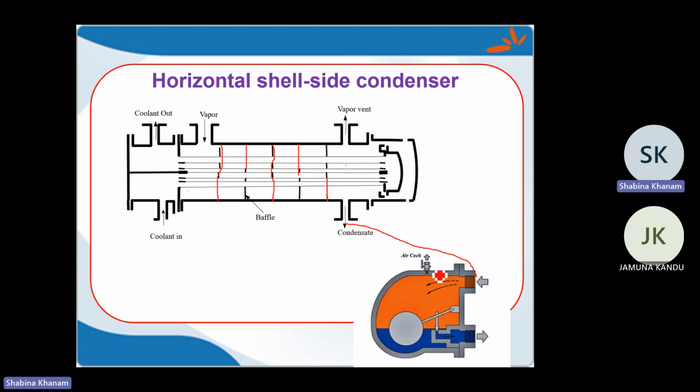Here it is completely sealed, and here I am having this balloon, and that balloon will be connected with this valve, this gate. Now what will happen is, when condensate and steam both enter, because of the density, condensate will settle at the bottom and steam will remain at the top.